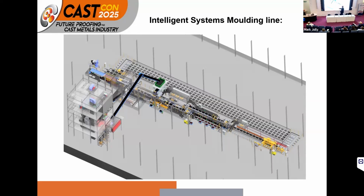For example, for the sand supply, there can be a device measuring the sand properties to make sure that the sand has the right quality before it comes inside the machine. In the summer, it can be that the sand dries out, or you have long ways between the sand preparation and the molding line. You avoid this with these systems.